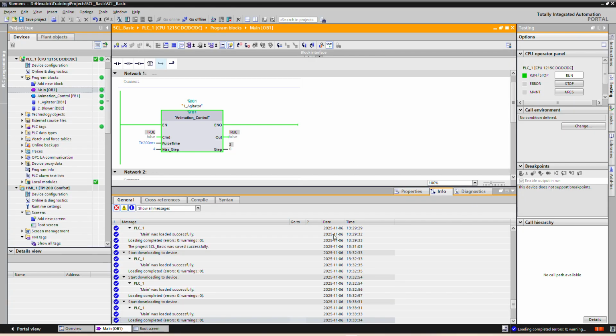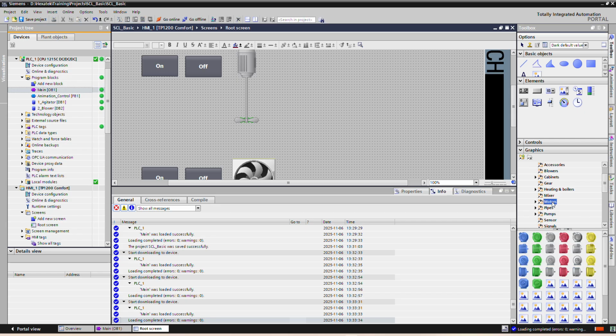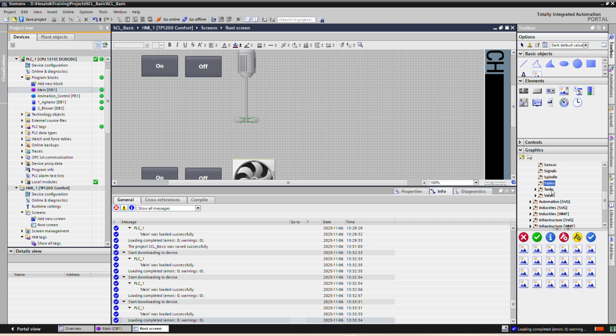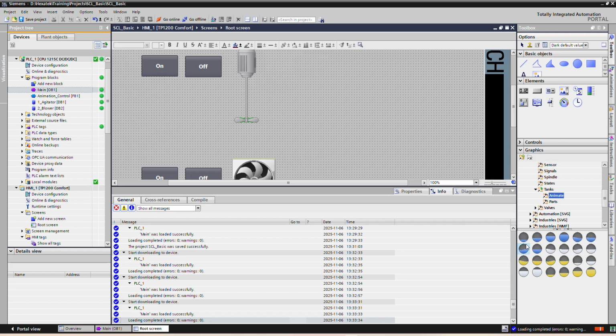In this way there are a lot of objects where we can provide dynamic animation: for the motors, the pipes, pumps, okay, for the tanks as well. There are dynamic levels we can show here. See this, we can attach this integer, our step value, to these 4 objects, and we can show it animated. Okay, thank you.